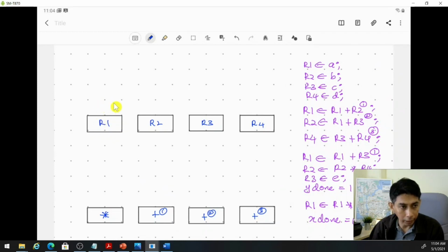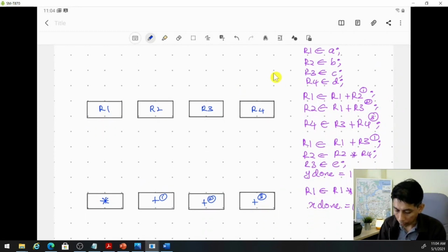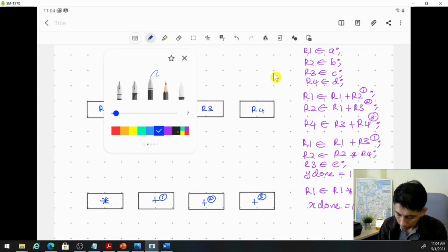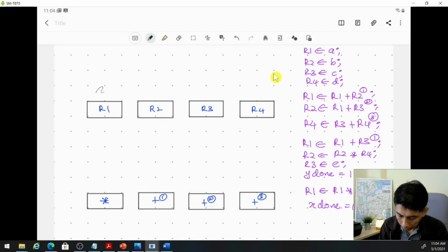So we have 3 waiting out here to enter 1 input here. So it means that you need a multiplexer just before R1 to select which one goes into R1 at one particular time. So let's draw the multiplexer like this, using one line only.